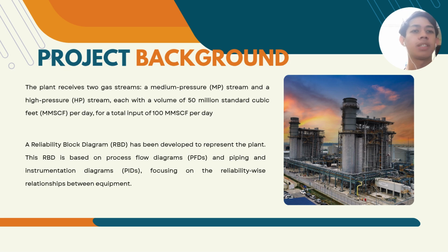a reliability block diagram has been developed to represent the plant. This RBD is based on process flow diagrams and piping and instrumentation diagrams, focusing on the reliability-wise relationships between equipment.